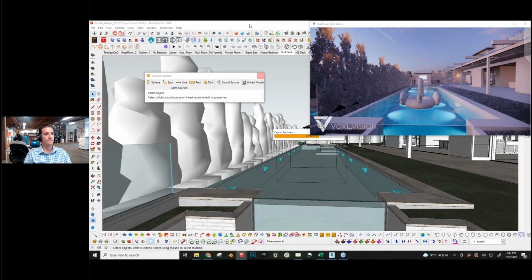But if you are trying to find a function that will get elements from your library to other applications like Revit, Rhino, and so forth, you're going to want to look to the Enscape custom assets functionality. That's going to be the best way to get elements from one platform to another the fastest.